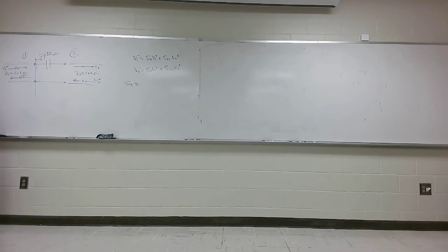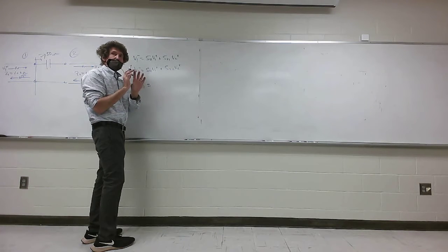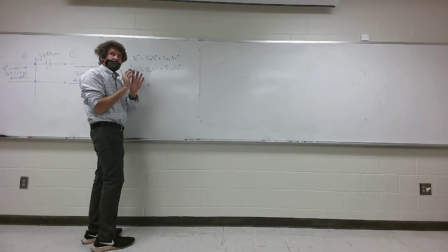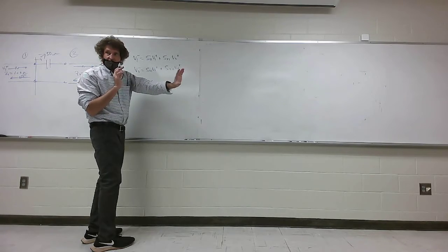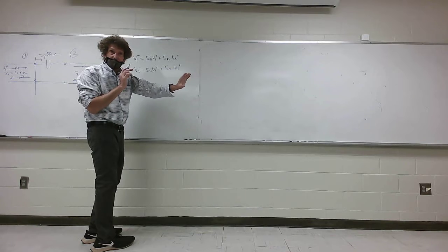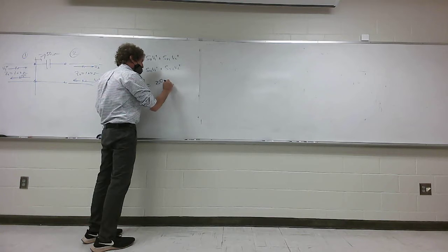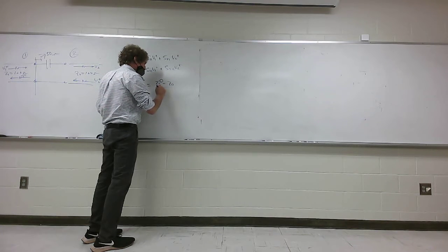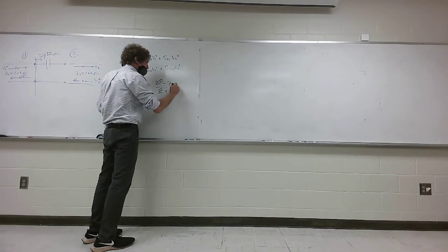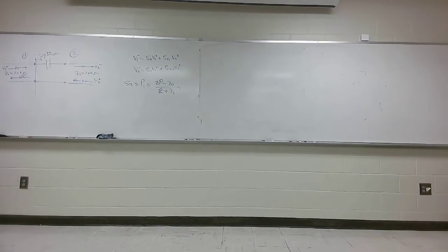What's the key thing? What do you know about reflection coefficients on port 1? You need one piece of information right off the bat: the input impedance from port 1 looking into the S parameter device. So I need Zin on port 1 minus Z0 over Zin port 1 plus Z0. What is Zin at port 1 anyway? Just like 50 minus j50, 100 minus j50.